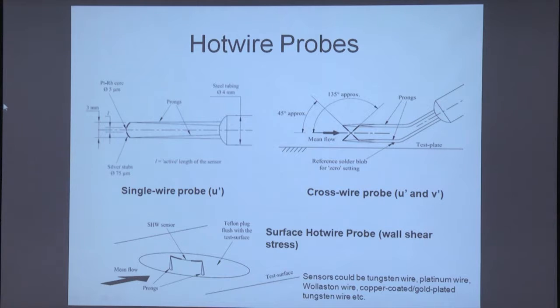where it's a tungsten wire, you directly heat it, you are in business. Typically tungsten wires are of the order of 5 micron, that's your sensor. We use what is known as a Wollaston wire. It's platinum rhodium alloy coated with silver, where there is a central region which you etch out by an electrolysis process and expose. You can see that here. And it is this active part of your sensor. So when the flow goes over this part, it will respond.